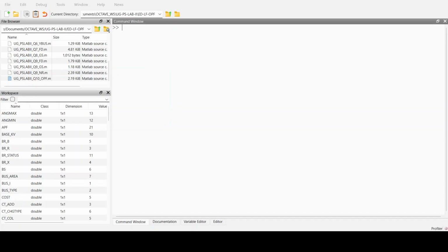So this loads the IO package. Similarly, you can load the Optim package. If it is available, it will be loaded, otherwise you have to install it. This Optim package may be necessary for MATPOWER. So you just check your run. If optimal power flow is not running properly, you can check for the Optim package or go through the MATPOWER documentation.